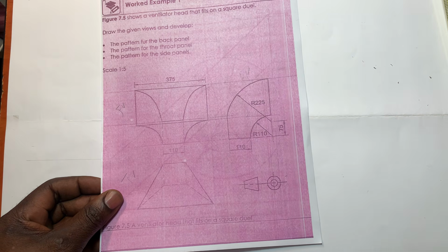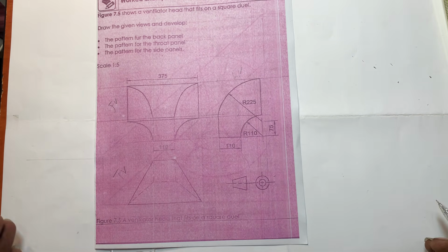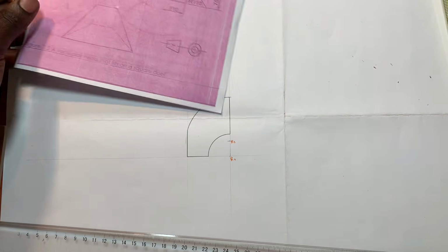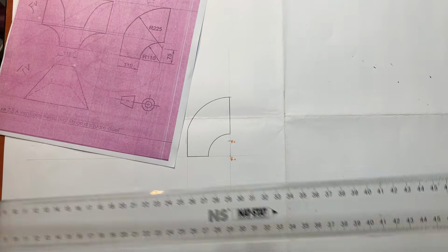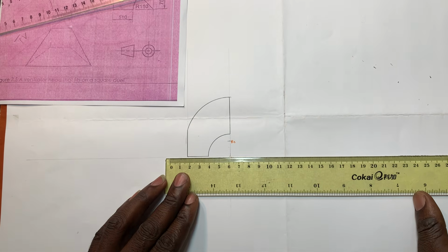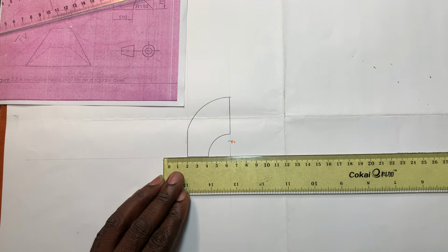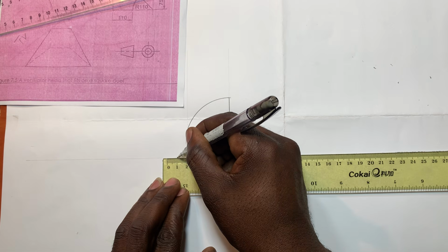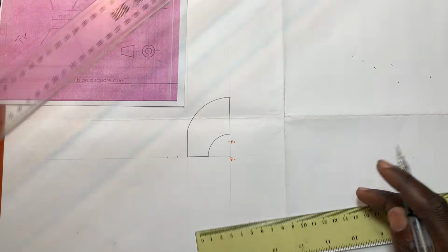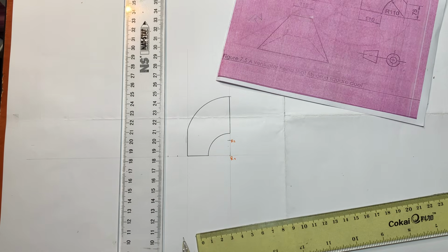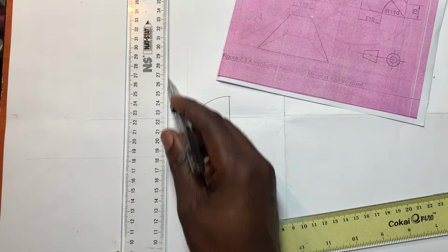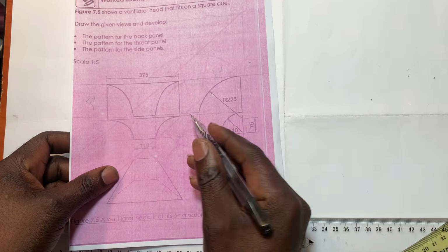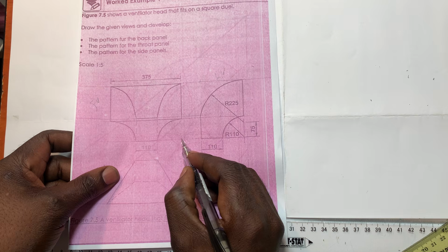You understand? Okay, so we are done with what? With the left view. We're done with the left view. So now we can approach to draw the front view. So I'm going to separate my views with 20 millimeter. Then I'll mark it 10 and mark it 0. So after that, I can have a vertical constructional line that's going to be like this. Then from there, which means that 20 is from here till right there.